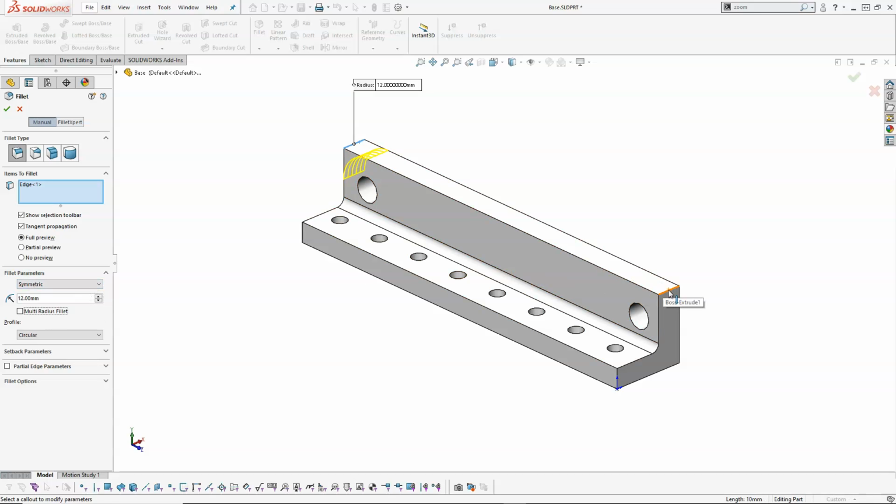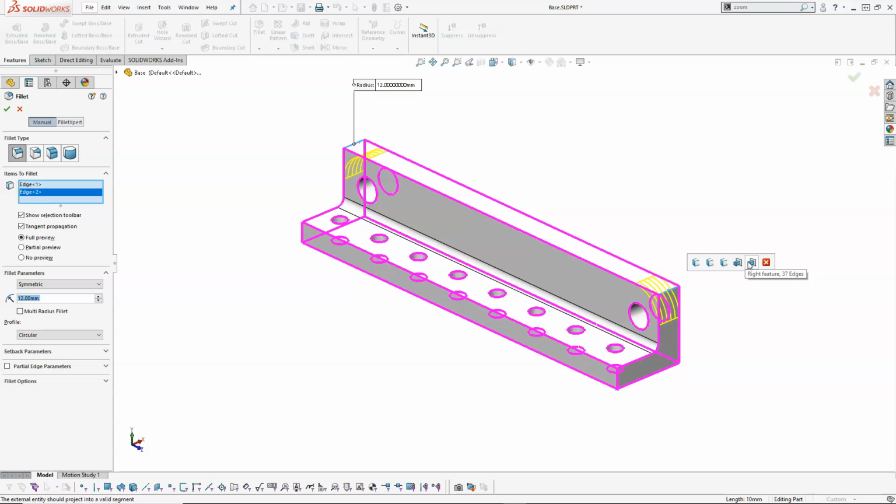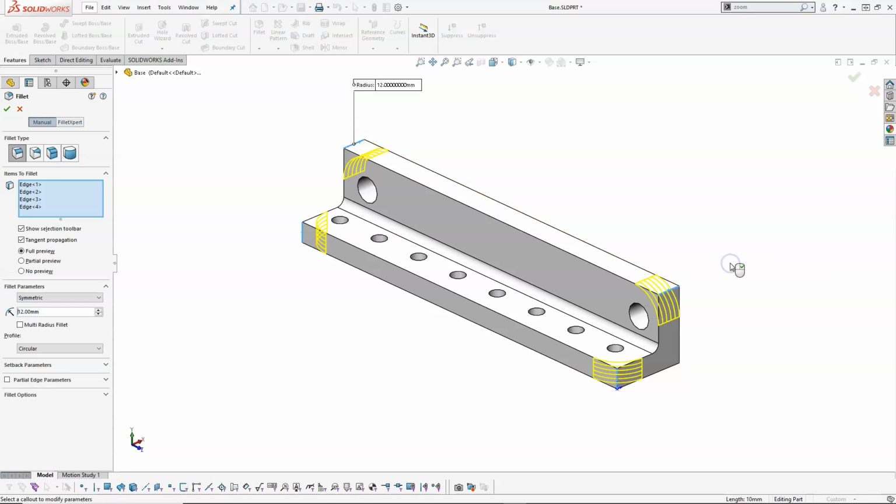When I select the next edge, if I pause before moving, then it's going to give me a selection filter. So I can pick all of the edges. Alright, and if I go to connect to end, that's everything. That is really everything. Alright, so which one did I like? I think that one. And those look pretty good.